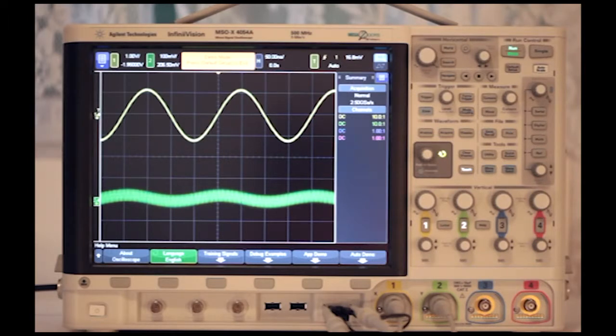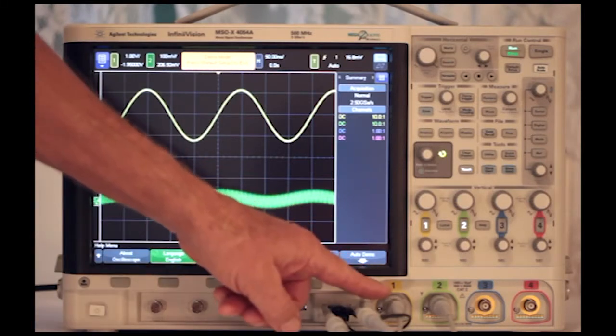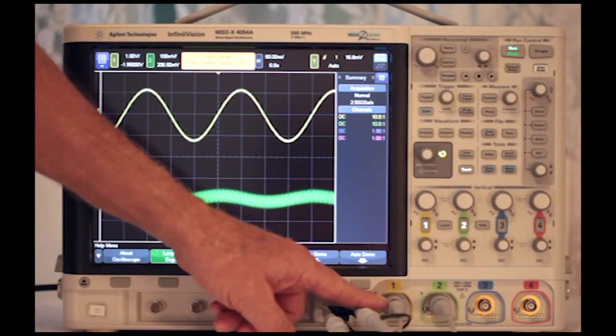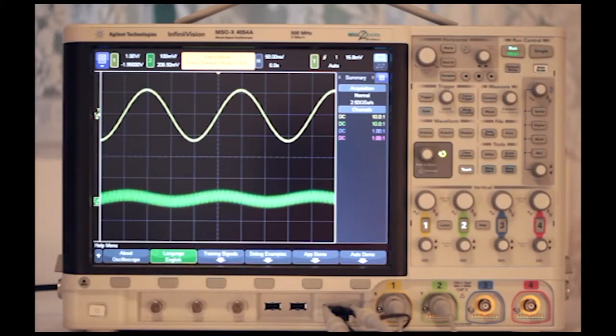Connect the probes to the proper terminals and to analog channels 1 and 2, being careful to have good connections and the correct channels. Turn on the oscilloscope, and after it is finished booting up, press Default Setup to clear any unwanted screens from the last work session. Sometimes channel 1 only is active. Don't worry, the oscilloscope will turn on channel 2 as needed.